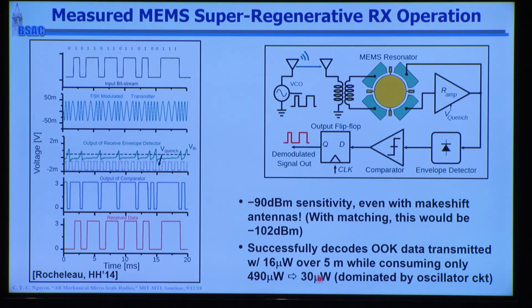And the reason why we're able to do this, let's bring it all the way back to the front. We've got that RF channel selection at the front that allows us to use a very nonlinear receive circuit that then allows us to take the power all the way down. Okay, so the whole concept, the whole system is working at least in this simplified circuit here.